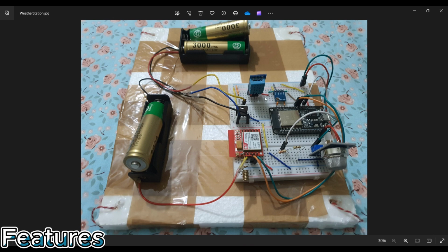Now, the monitored weather parameters, the 4 or 5 parameters that I've already told you, must be shared with the user in real time, and there are a number of approaches to do so, and I've followed the GSM based approach where you simply have to send an SMS to the SIM card which is inserted into the SIM 800L GSM module, and then the SIM 800L GSM module will be sending you back all the monitored information of that time, like the air temperature, the air humidity, the atmospheric pressure, the altitude, and the presence of gas or the percentage of gas at that atmospheric level.